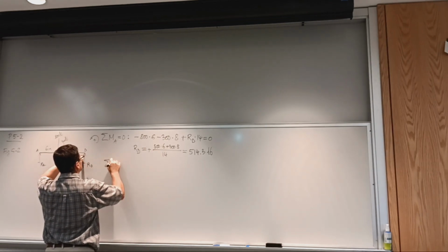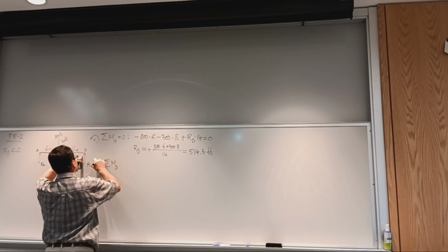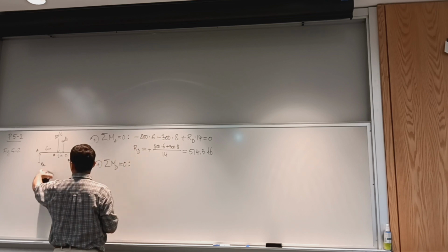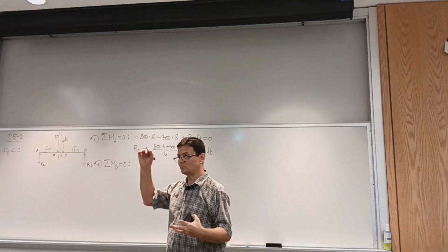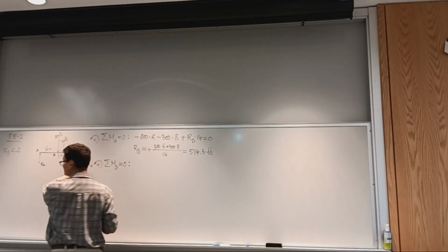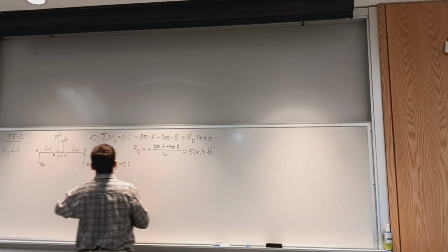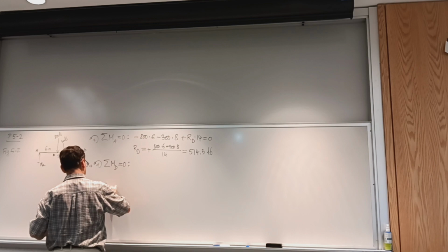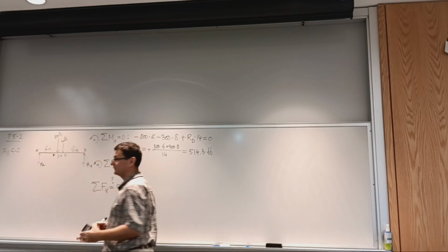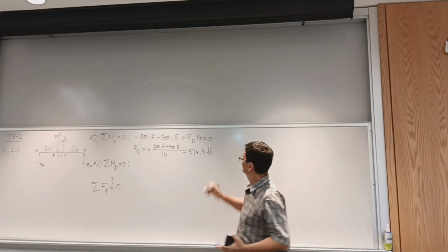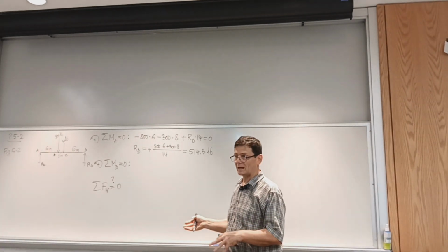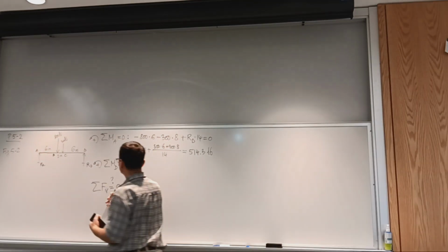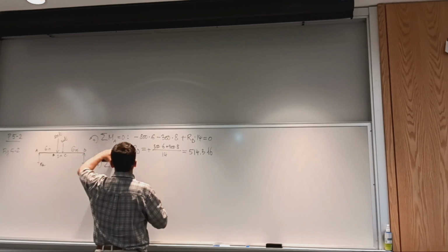So sum of moments about point D, likewise consider positive counterclockwise, equals 0, equilibrium. This will allow us to calculate RA. I'm not jumping to using the sum of forces in the y direction to find RA because I may have a mistake here. The last step will be the sum of forces in the y direction, or vertical direction, equals 0, with a question mark. If it ends up very close to 0 because of round-off, I can move forward. Otherwise, it's useless. You invest time in drawing the diagram, shear force and bending moment diagrams, when your reactions at the supports are incorrect. So what do we write here?